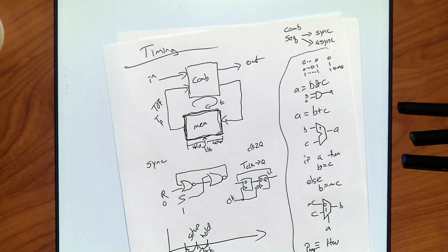But it's going to be pretty slower than the speed of light. And it's not just that. Now you have to deal with the permittivity and permeability that's going on, which is going to change things. But even more so, you probably have an effective RC circuit. You have wires near each other, which is going to provide some capacitance between them. There's resistance down the wire and things like that. So this is even slower.